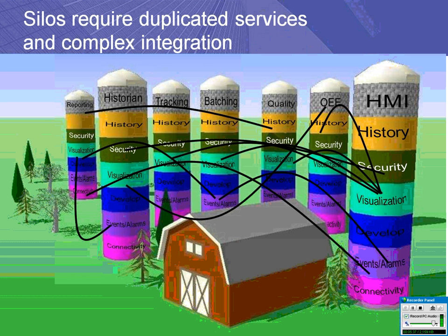Now the idea behind System Platform, or one of the ideas, is it becomes a centralized development environment for configuring all of these products. So from within System Platform at the moment, we can configure our historian, we can configure our HMI, we can configure OEE using our performance module, and we're getting towards being able to configure the other products. For example, when the next release of InBatch comes out, then that will have a lot of work done from within System Platform.